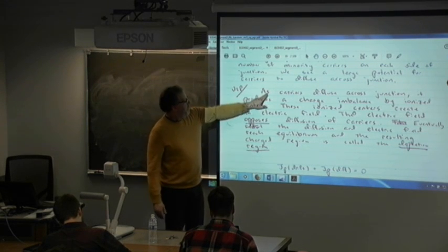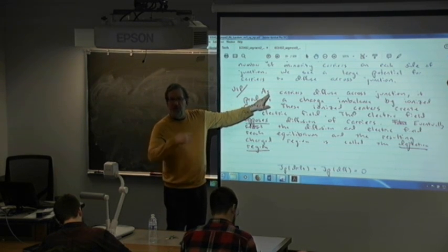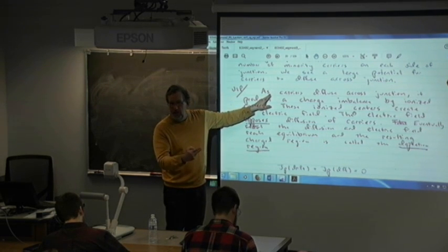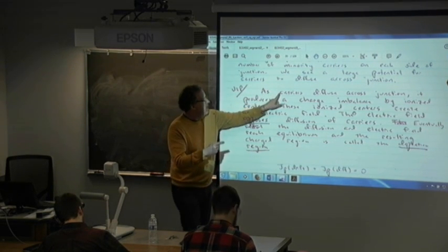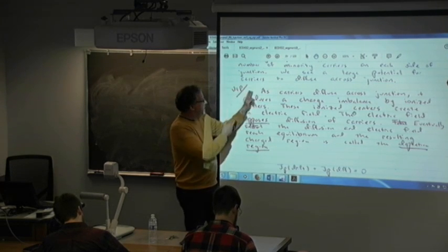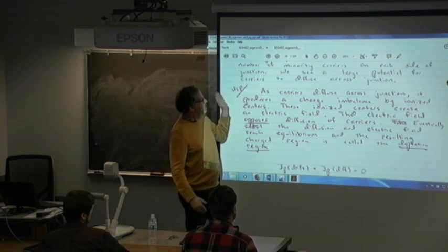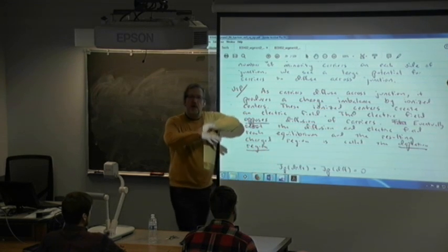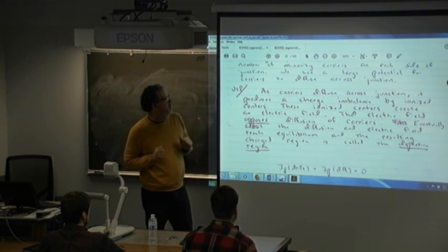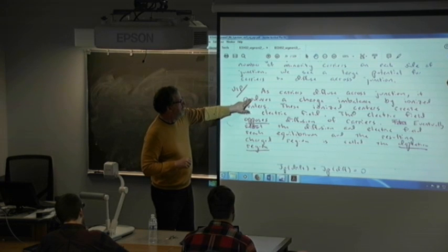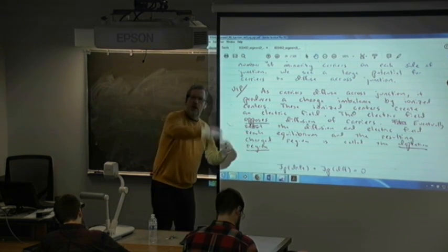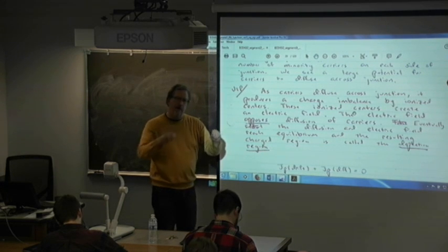So, what I forgot to talk about here is what's the starting point. The starting point is the concentration gradient. So concentration gradient is assumed at that point, and that means that the carriers then diffuse across because they're trying to equilibrate the concentration gradient. But as they do so, they're creating this charge imbalance because the electrons going across are not coming for free.